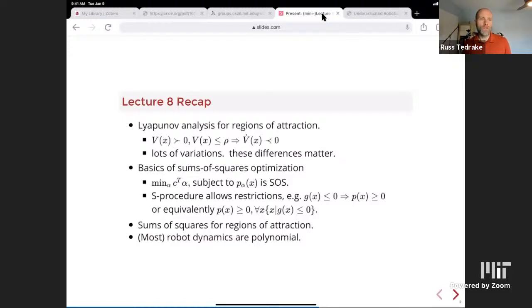So the statement of using LQR is basically, the more general statement is, if you can take some fixed point that's stable by a controller, or is just a simple system that's already a closed loop system, and the linearization can reveal that it's stable, then a quadratic Lyapunov function found with the standard Lyapunov tools for linear theory can give you a good guess. And then you could ask, for what region does the linear cost to go function, the quadratic Lyapunov function, also certify the nonlinear system?